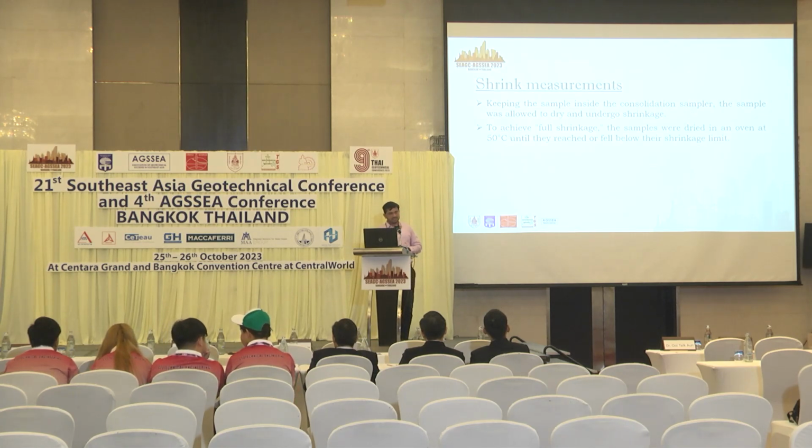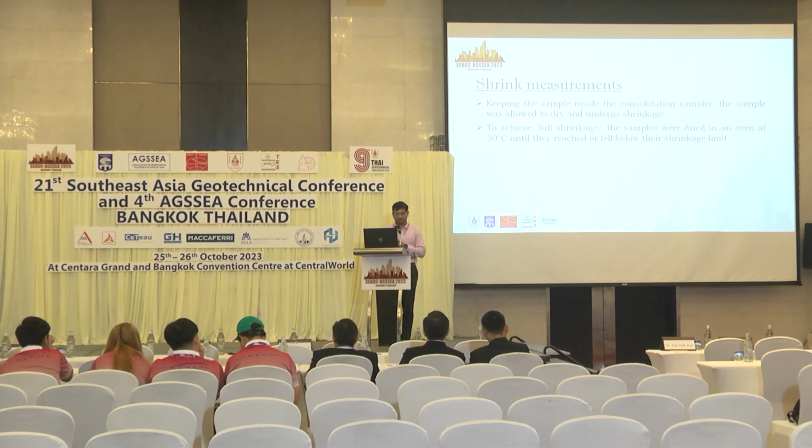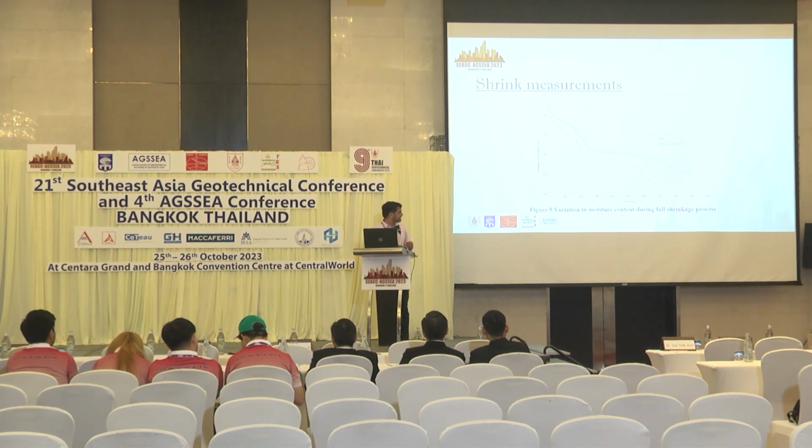The shrink measurement was done on the sample collected from the oedometer testing. For some time it was allowed to dry at ambient temperature. Then I put it in the oven at 50 degrees Celsius, and I measured the volume and the weight at particular time intervals. And these are the graphs for the shrink measurement.